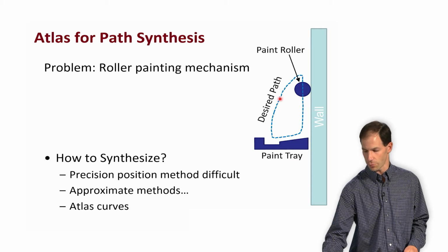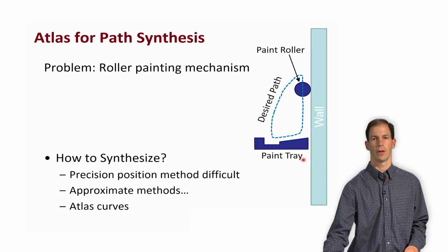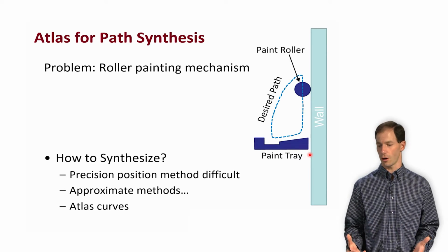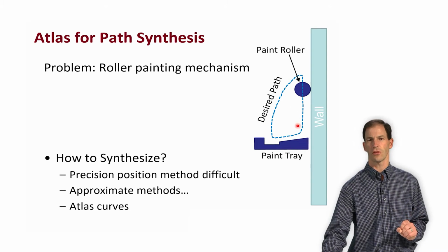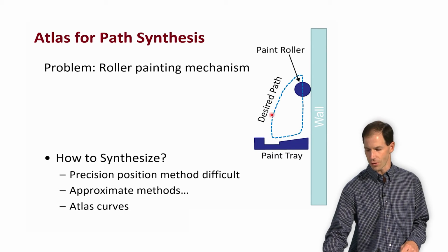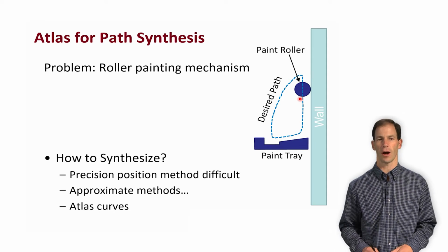And if I could add a 4th maybe to help guide it through the motion. But I really don't know what it's going to do in between. So how can I help myself? Well, there's some approximation methods where I could have more precision positions, but they're approximate. Or perhaps I could go to an optimization method, so I could say this is the path I want to follow, and then I could optimize it as close to that path as possible.